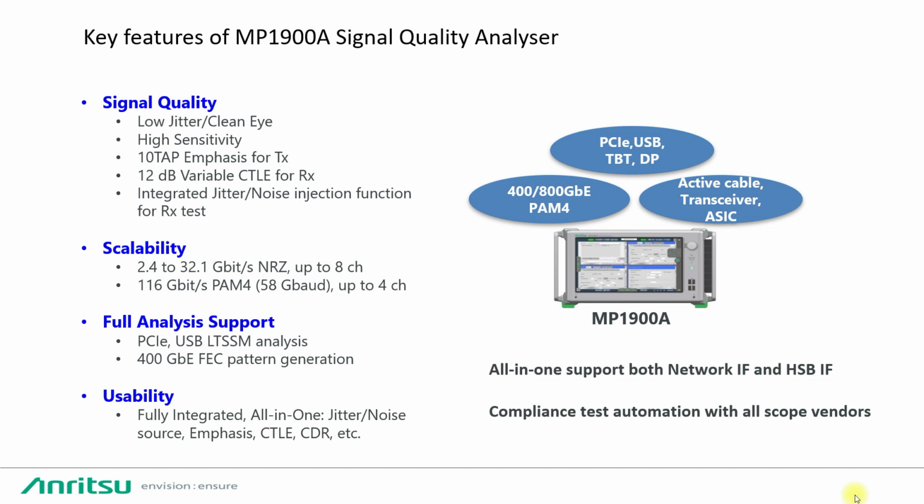PPG and error detector are protocol aware to bring PCI Express and USB DUTs into loopback mode during a successful link training. I'll come back to this topic soon.